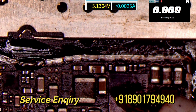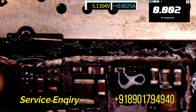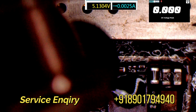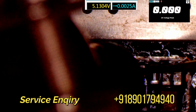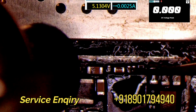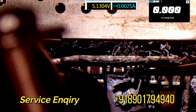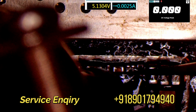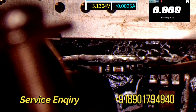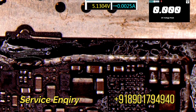A little flux here, right. And my heat is 350. Now we clean this IC.